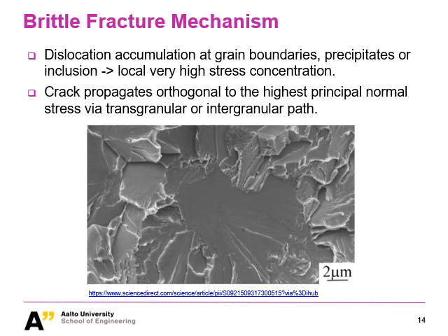The second point, of course, is on crack propagation. As you probably noticed from the figure on the previous slide, the crack just propagates perpendicular to the highest principal stress, via either a transgranular or intergranular path. I think from your solid mechanics lecture, you have already learned what principal stress is and what is just random stress.